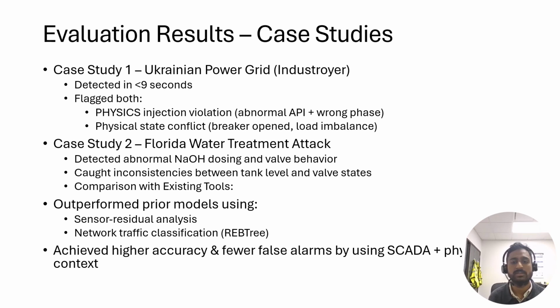Case study two is the Florida water treatment attack. They have detected the abnormal sodium hydroxide dosing and valve behavior. They caught inconsistency between the tank level and the valve states. They saw that, let's say, the tank already had high dosing, but the valve for the sodium hydroxide was still open. So this was seen as a physical state conflict, and Scaphy detected that.